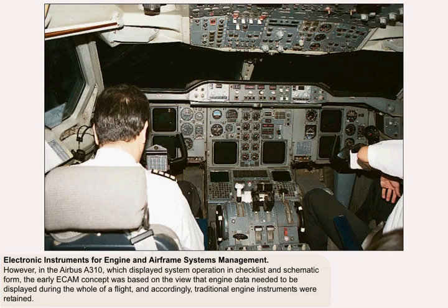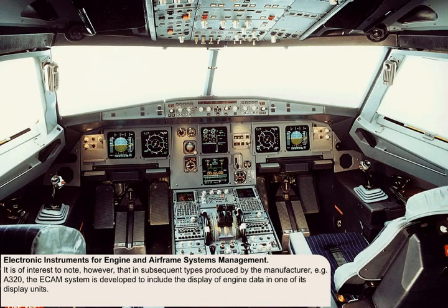However, in the Airbus A310, in which system operation was displayed in checklist and schematic form, the early ECAM concept was based on the view that engine data needed to be displayed during the whole of a flight, and accordingly traditional engine instruments were retained. It's of interest to note, however, that in subsequent types produced by this manufacturer, for example the A320, the ECAM system is developed to include the display of engine data in one of its display units.